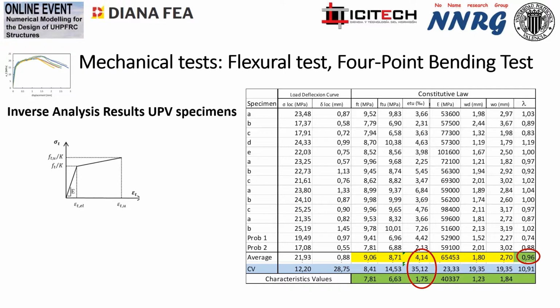And it's easy to have multi-cracking only thinking of the variability of the sectional properties. You can see that in our mix concrete, with 160 kilos of fibers, we have a strain of crack localization close to 4 per mil, with big variability. The figures of Eduard can show some problem of credibility because of the big variability, but even in this case you have close to 2 per mil of strain with controlled crack, working in a material at the limit of softening and hardening. That is the element we usually work with, and we also work with more softening material properties. Those are characteristic values.